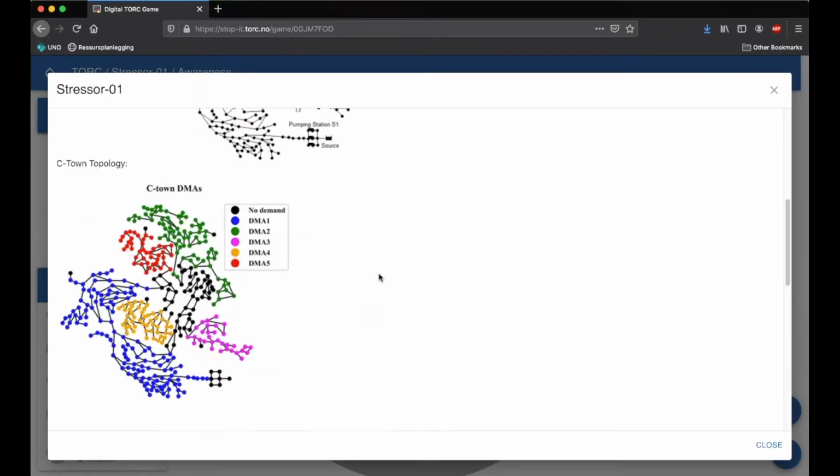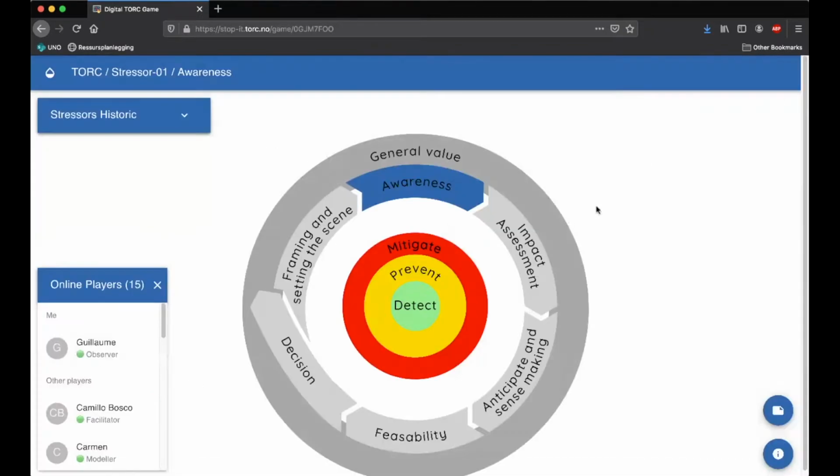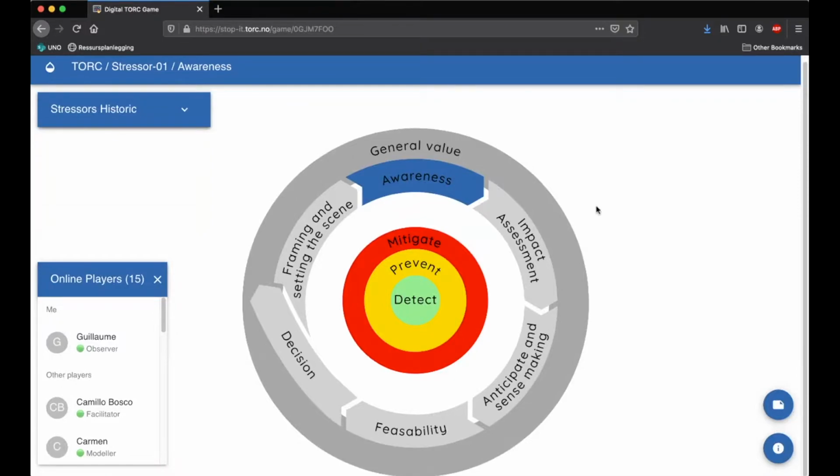So basically, an engineer of the control room now has to find out why there are these complaints. So he can look at the data of the sensors he has in the network. First of all, we have the possibility to check some pressure meters and also the flow meters in the pump. What would you check in the place of an engineer of the control room? First, among the sensors, flow meter, the pressure sensors.